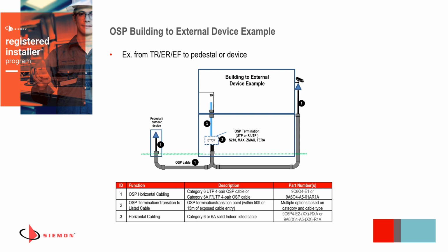And I did mention earlier, if you did use indoor-outdoor cable and that was a plenum environment, you wouldn't have to make that transition. You could just come right into the building and route it directly up to your telecommunications room without the transition. So it's important to know what the environment of that cabling actually is from when it enters the building to where it actually will terminate.